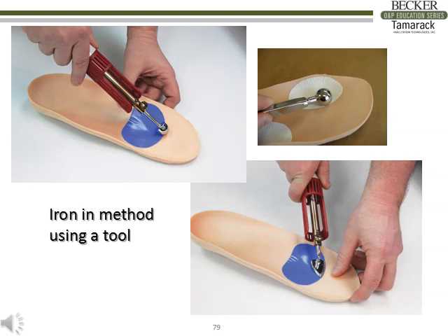If inlaying is not possible by the methods shown earlier, using a heated tool as an iron is another way to smooth and recess edges down into the foam insole. The tool can be self-heating or heated with a heat gun. Care needs to be taken not to scorch the film or the insole material, and ironing too long may delaminate the layers of the interface patch. Skills doing this are easy to acquire with little practice.